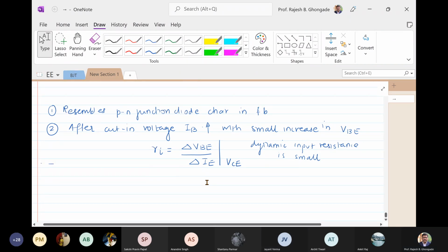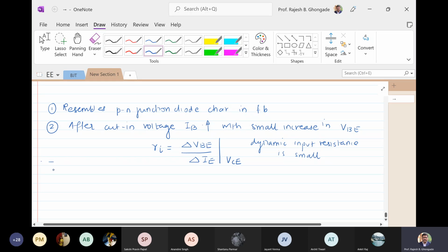Yes, sir. Okay, observation number 3. For a fixed value of VBE, IB increases as VCE is decreased. Let us see that.